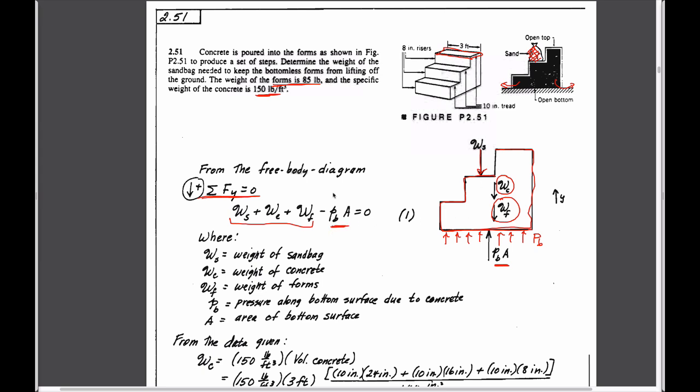And so this perhaps is the wrinkle in this particular expression, in that we have to figure out what p would be. And it's kind of interesting because we have a height of fluid here, which is step 1, a height of fluid here, which is step 2, and a height of fluid here, which is step 3. We know that within any system, on any horizontal plane, the pressure on that plane at any point is going to be uniform.